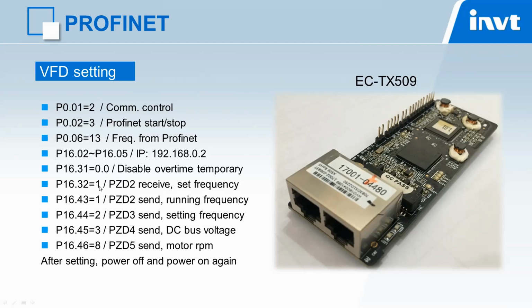P16.32 equals 1. This is the PZD2 receive. When we want the PLC to set frequency, we write the data to the PZD2 receive for set frequency.